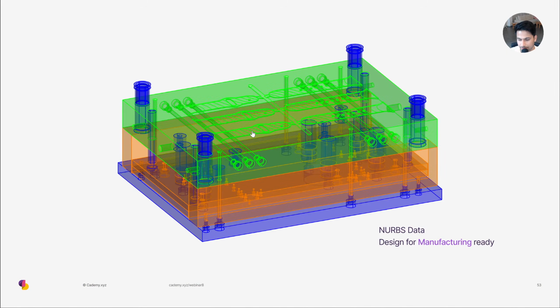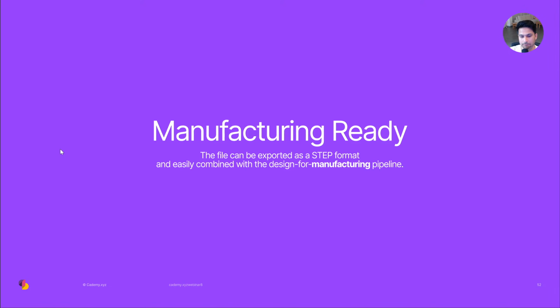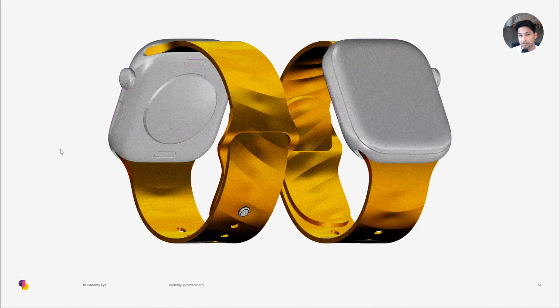How can I render in KeyShot with a hand? I will recommend you to look at different mockups, because in KeyShot you can provide a front image or a back image, so you can maybe create your own picture and put it as a background image.